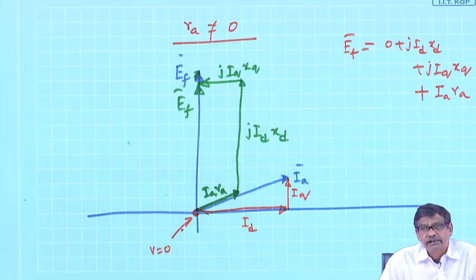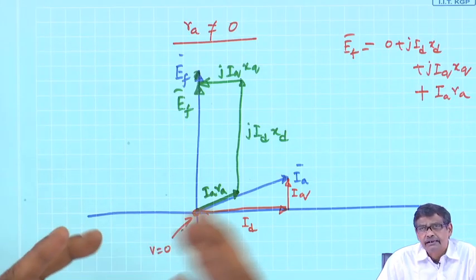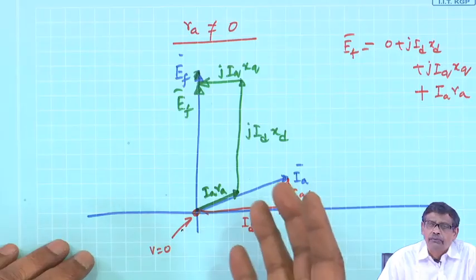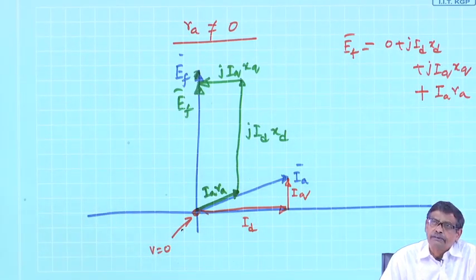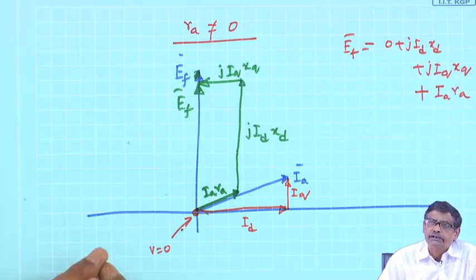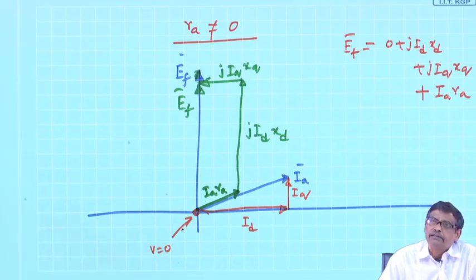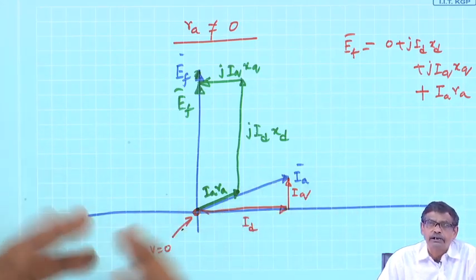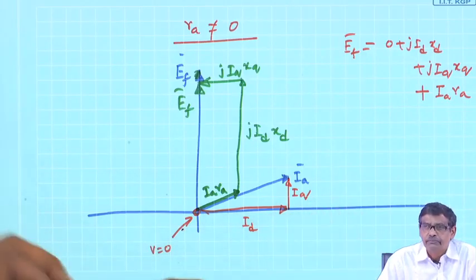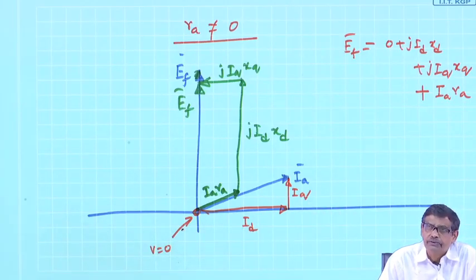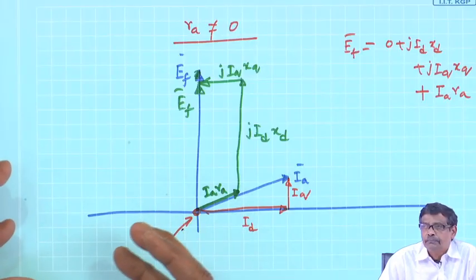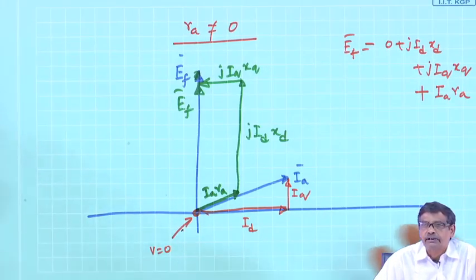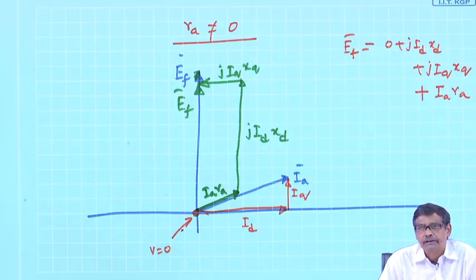Then I took up the single phase induction motor. The analysis of the single phase induction motor was based on the 3-phase induction motor only, although it is slightly involved, because I showed that a single phase induction motor develops a pulsating field which can be broken up into a forward and a backward field. Therefore, those two induction motors can be used individually, as if positive sequence and negative sequence components are two individual machines; find out the torque from them and take the difference.